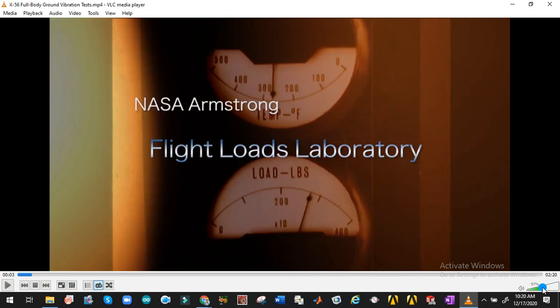Okay. So, two domains are covered separately. One domain will be covered in the mechanical vibration class, that is the analytical problem. Another domain will be covered in the ANSYS class, that will be your DME lab, and the third way is to solve the mode shape in the laboratory environment, by experimentation. How can we do that? We need a scaled down model of the aircraft wing, and we need an exciter as well, a harmonic exciter. We will connect multiple vibration transducers at multiple places of the aircraft wing.